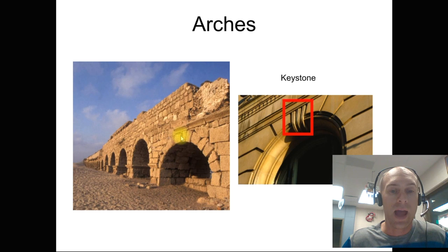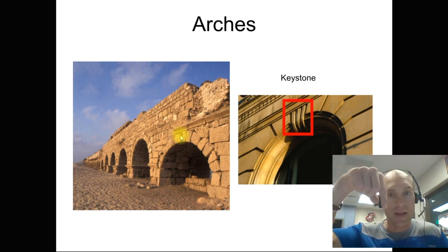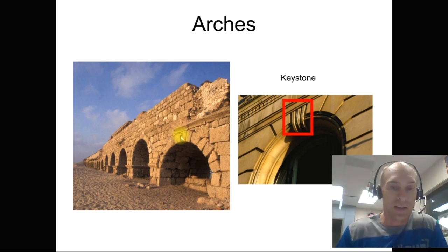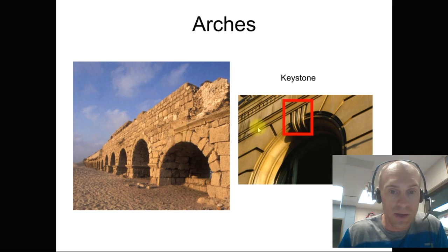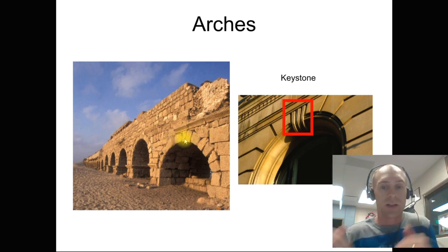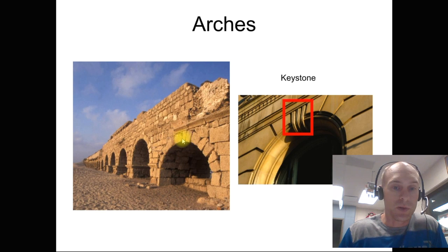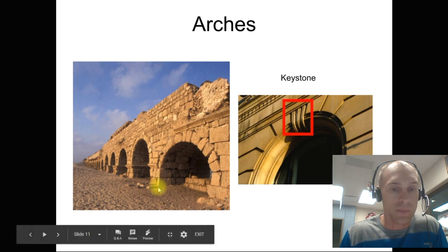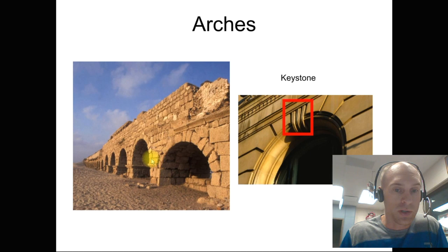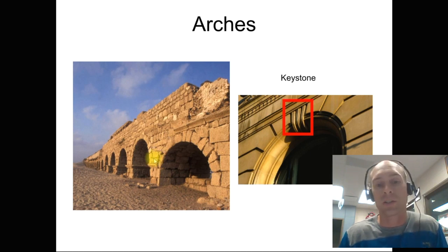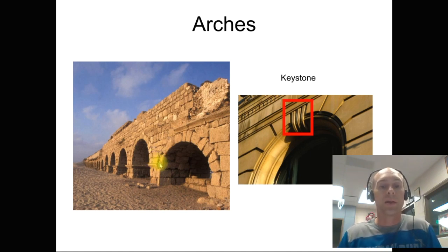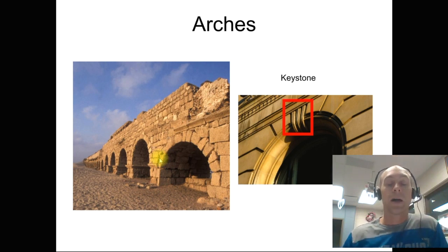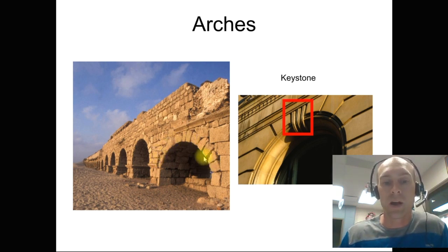This keystone, as it gets pushed down, then those forces go out because that stone can't go down anymore because there's other stones that are kind of locking it in place. So this one goes down, those forces go out, that next force goes out and down, out and down, out and down, out and down, all the way down to the bottom. It's pushing out this direction, but this arch is pushing back onto this direction, so they kind of hold each other up. So the arches were designed because the Romans decided, hey, we want to bridge even larger gaps,